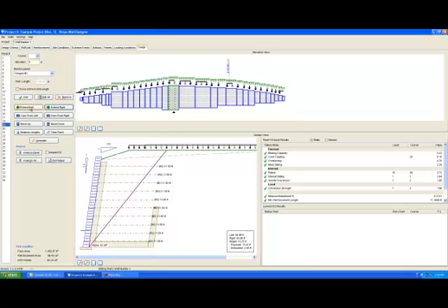Keep in mind that at some point someone will have to construct this wall. The designer should always balance an economical use of Geogrid with a reasonable level of complexity in terms of the installation. By keeping the geogrids at consistent elevations throughout the wall, which is automatically done with the extend functions, we are preserving a consistent pattern for the contractor to lay the geogrids out. Over complex designs, that is, constantly changing geogrid lengths and elevations done in the name of economizing geogrid, often cause more problems during installation and potentially down the road.